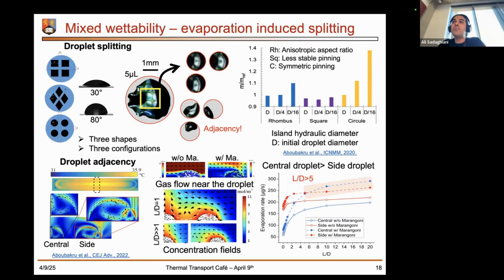But in terms of mixed wettability, what I would expect is some enhancement compared to, for instance, hydrophobic or oleophobic surfaces, or a pure homogeneous surface. But for the design of the mixed wettable surface, I would suggest considering the surface tension and the latent heat, accounting for, for instance, hydrogen at that temperature and pressure.